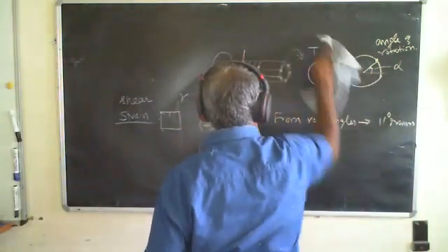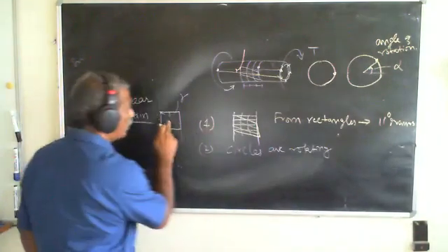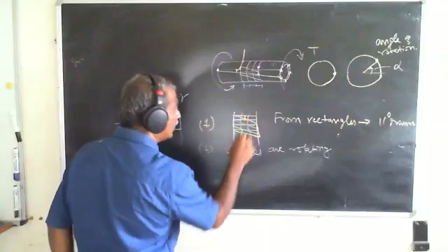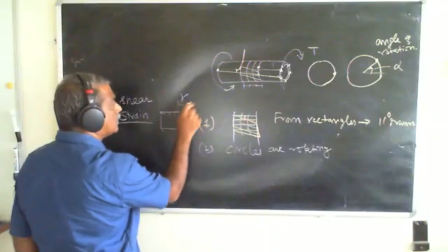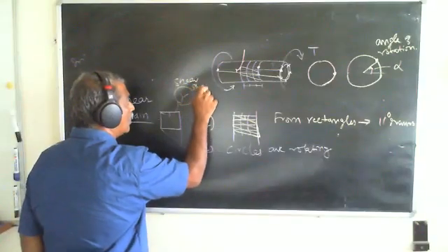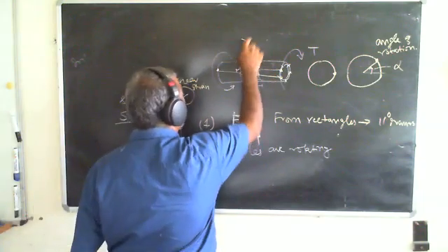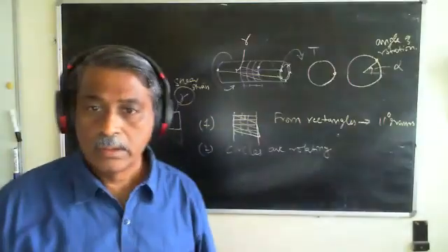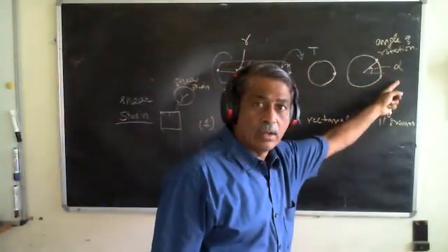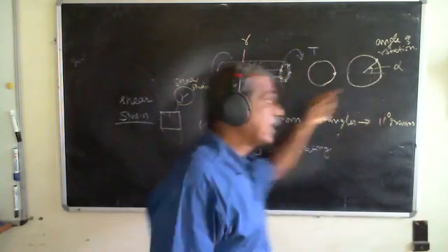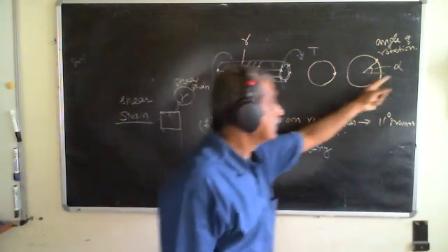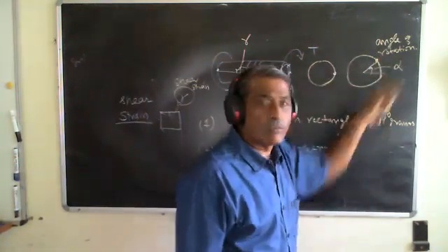Now, what were straight lines over here have now become slant lines here, and this angle is the same as this angle, which means we are looking at shear strain as the angle that is formed over here. So far, so good. Is this clear to you? One is the angle of rotation of a cross section that I've taken compared to a reference over here, and let's say that is alpha. I'm going to call that the angle of rotation.